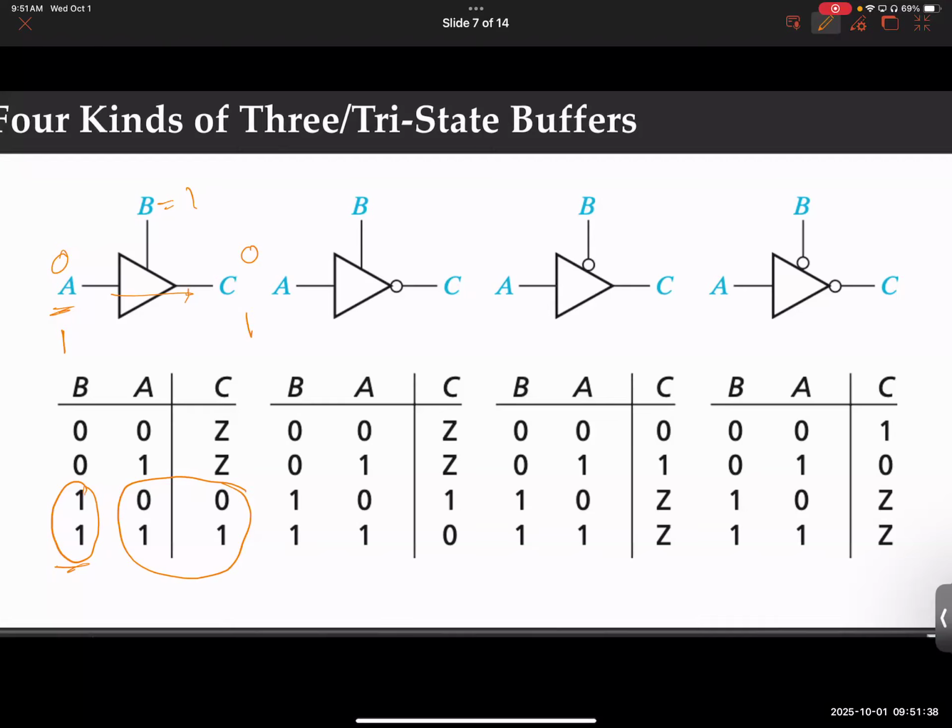Okay. So when we read from SRAM, before we read, we charge up a node and let it float. Literally, and I'm using the term float. You make the node floating. You don't drive it. You don't make it zero. You don't make it VDD. You just let it do whatever it wants to do. And you basically see, have you seen someone measure your blood pressure?